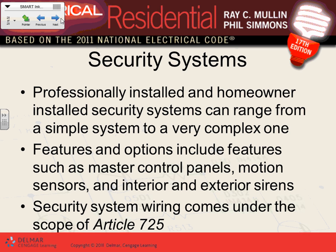Carbon monoxide detector, you need at least one. So make the one in the living room your carbon monoxide / smoke detector. They're all going to be interconnected, and they're going to be the combination type in our project. That means the alarm and the detector are all in one. Okay.